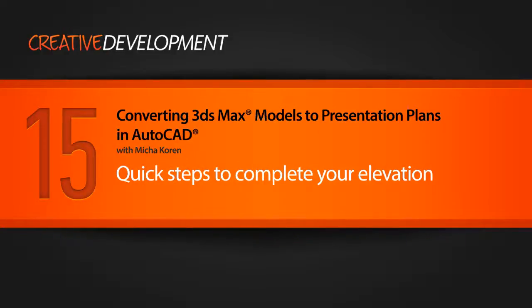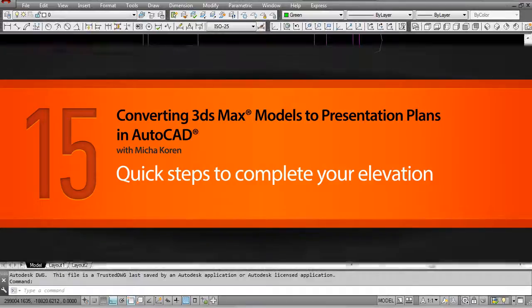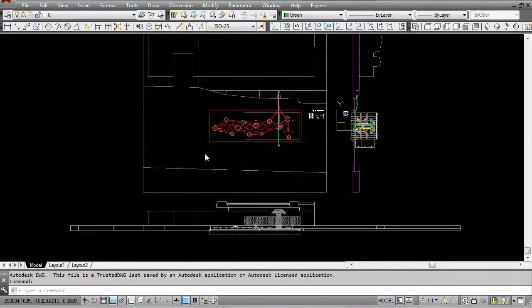In this lesson, we'll learn how to speed up new drawings by using existing elements. What we have in front of us, and what has happened since the end of the last lesson, is that all of those 3D elements that were pulled in from 3D Max have been flattened using the flatshot command. We have basically merged everything together exactly the way it had been done with the section. I haven't re-shown you the process for this elevation because it is identical to what I did in the last couple of lessons while doing this section.